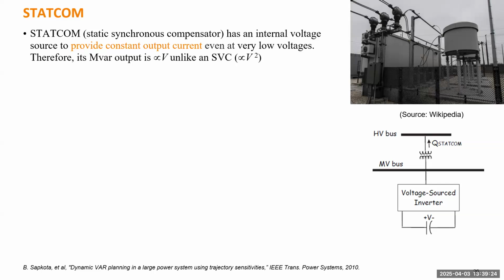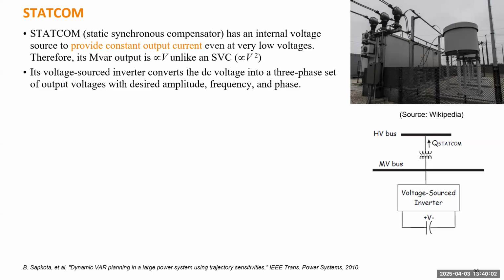So the question will be whether the manufacturer and operator really desire them to operate as STATCOM. Operating as STATCOM means under some conditions or in some operation mode, the main purpose is to provide reactive power, to provide a high inductive current to the system, but not a capacitive current. But that may not be good for the life or the condition of these renewable energy resources. So utilities do place dedicated STATCOMs in there. It can be very expensive.